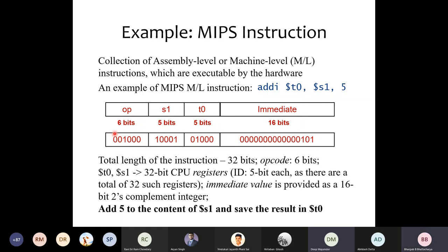Well, see, the thing is, you have a budget of 32 bits for the instruction, right? So now 16 bits are gone to designate the opcode and 2 registers, fine? So you are left with only 16 bits. So whatever immediate value you have here, that must be representable. This may be positive or negative. And whatever value you have here must be representable within these 16 bits, because you have only a budget of 16 bits left. Good.